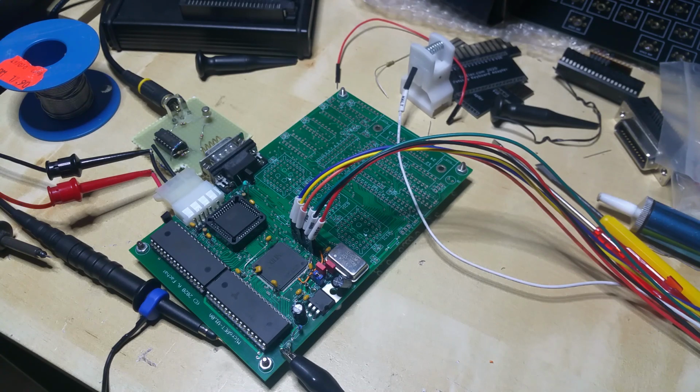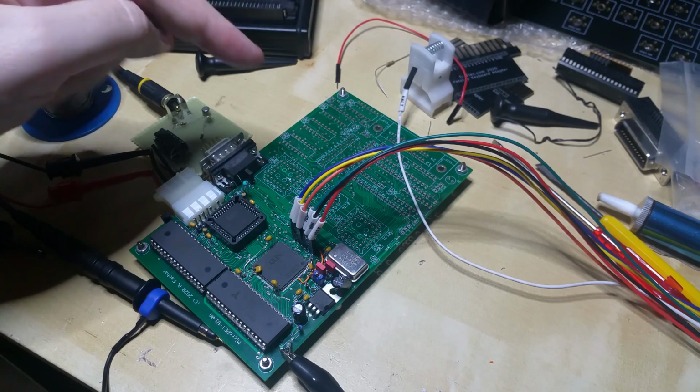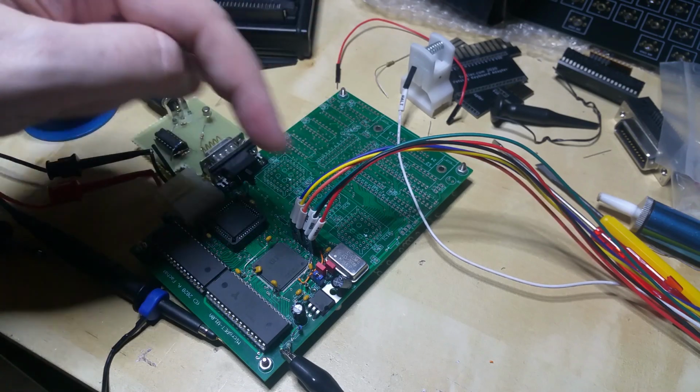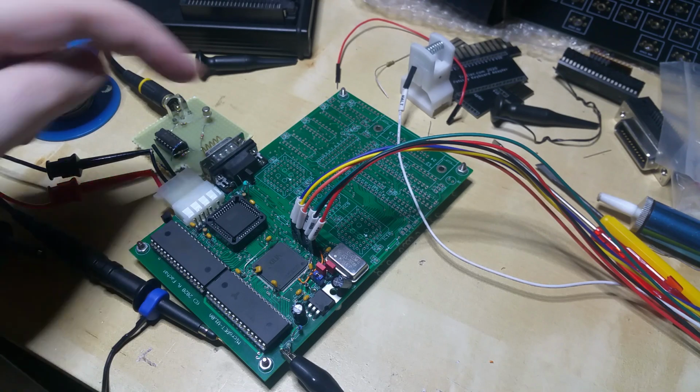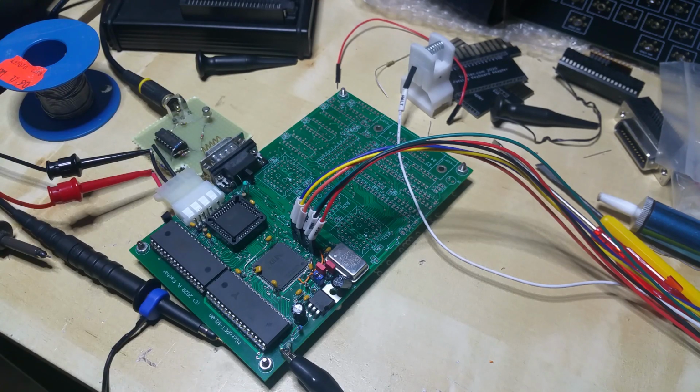The reason for this is that all the I/O that is here in the system, that will be here at some point in time, is 5 volt I/O, and also the I/O chips from Western Design Center, the PIA and the VIA, are only capable of doing 5 volts when they are run with 5 volts, and they don't allow signals on the data bus and so on that are above that supply voltage. So the CPU has to run at 5 volts as well.